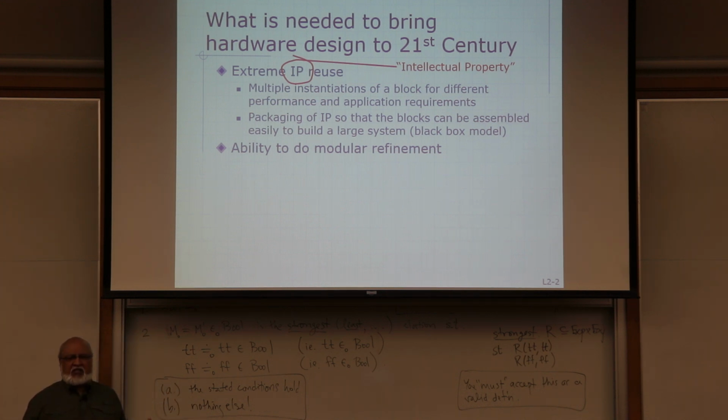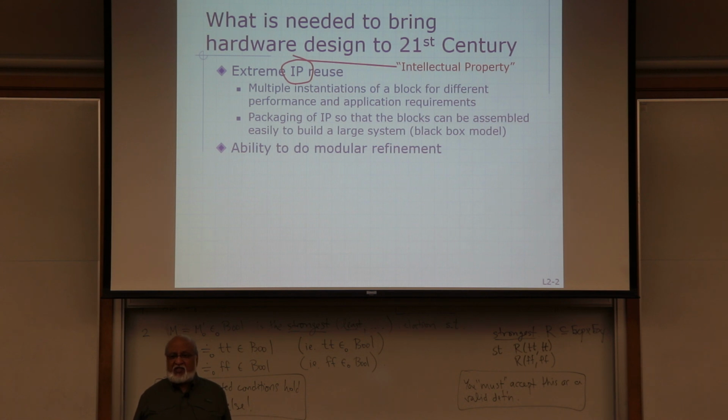Suppose I take a very common system. I have a processor memory system, right? I have a multi-core. I may have several processors and a memory system. It's conceivable that I have different kinds of processors connected to it. I may have, as it's called, wimpy processors, which may be just no pipelining or in-order processors, which consume less power, have less oomph in them, they don't compute as fast. And I may have a very fancy processor, which is out of order, which consumes a lot of power, but also goes very fast. And I want to connect them to the same memory system, right?